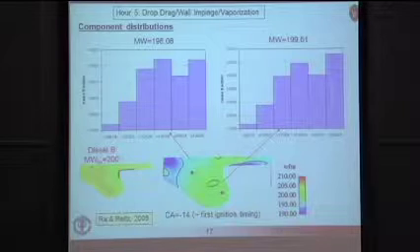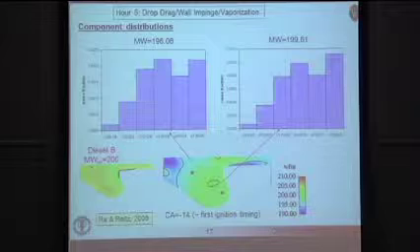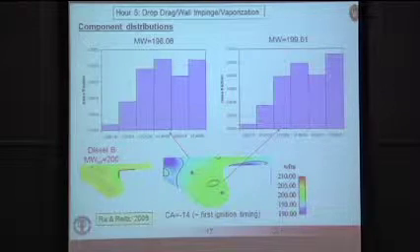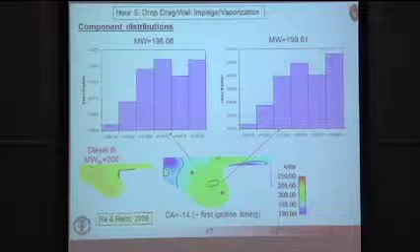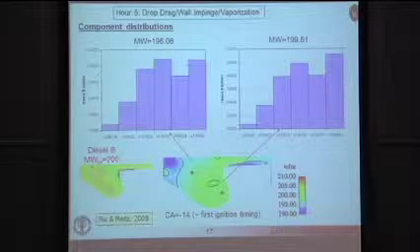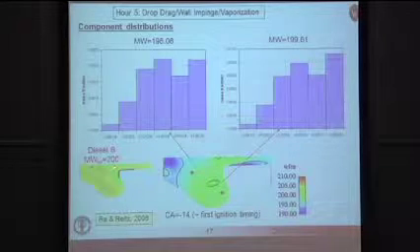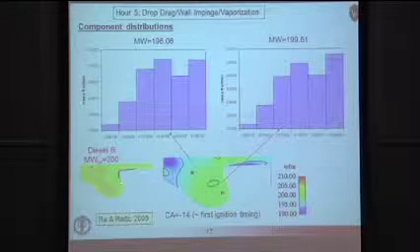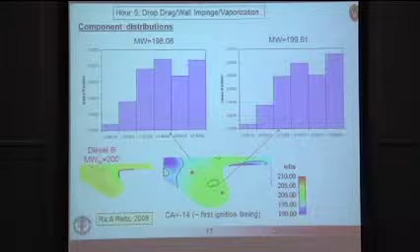We then did a simulation with the spray models that I've been talking about, integrated with the vaporization model. And what we're plotting here is essentially the molecular weight of the fuel. The injected molecular weight is 200. All right, so that's kind of in the upper greens here. And what you're seeing in the engine is the spray droplets. There's actually some impingement of droplets on a surface here. And the colors show the distribution of molecular weight.